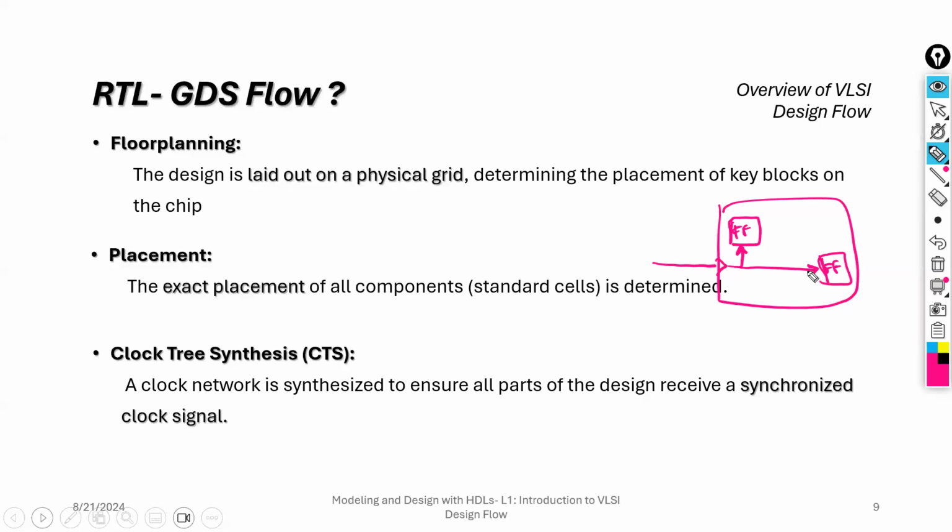That is possible only with the help of clock tree synthesis. With the help of clock tree synthesis, we are able to provide the clock synchronously to all the flip-flops. That is what our intention is. It will take responsibility of the clock tree synthesis mechanism. It will provide the clock to reach each and every flip-flop at the same time.